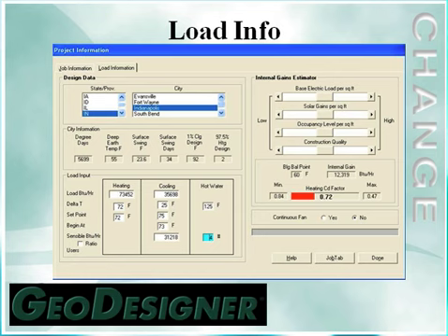The last input on this screen for us to select from is continuous fan operation. When we show an operating cost for heating, cooling, and water heating, we also have an option to show fan consumption, electrical consumption, and dollars operating cost. If we're going to compare to a PSC blower, maybe on an older existing system, and we're going to use our ECM fan motor, we all know there is some energy savings there, and it can be beneficial to show that to a consumer. Also, if we're going to recommend they run the blower continuous for air circulation, this would be the point we would select for that fan operating cost.